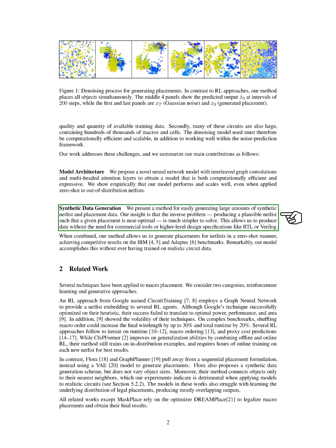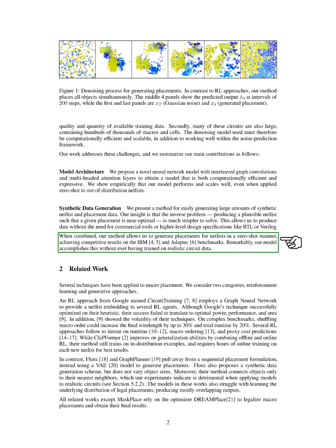We also introduce a method for generating synthetic netlist and placement data easily. By solving the inverse problem of creating a netlist for a given placement, we can generate data without relying on commercial tools or detailed design specifications. This approach enables us to produce placements for netlists without prior training, achieving competitive results on benchmark tests without using realistic circuit data.